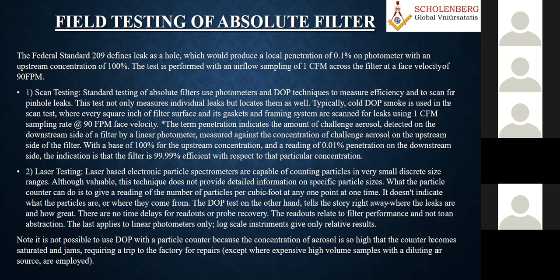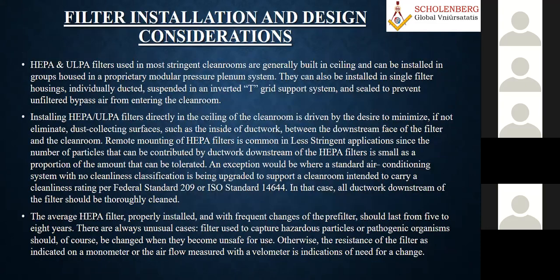So standard testing of absolute filters uses photometers and DOP techniques to measure the efficiency and scan for pinhole leaks. Similarly, laser testing, laser beamed electronic particle spectrometers are also capable of counting particles of very small size. This is all we will leave to the manufacturers of the filters. As I know, standard manufacturers like Camfil always follow standard quality material. For them, the filter is their family, their business. They don't compromise on quality. They follow all these professional standards.